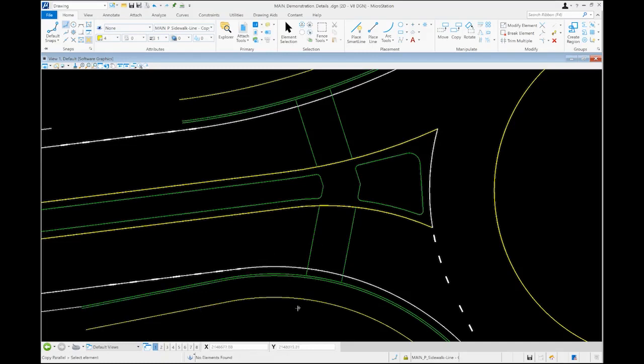And the reason for the 6-foot offset is it allows us to have a pedestrian ramp in there that doesn't require any sort of depression or adjustment within the multi-use sidewalk facility along the roadside. So all of our ADA ramp can be within this buffer area. And it also allows for some additional room for signing and things like that along the roadside.